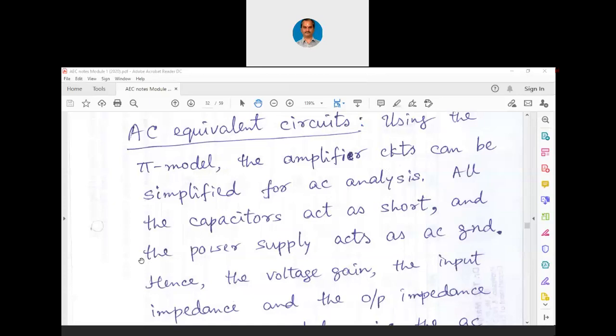In the previous class, we were discussing how to model a transistor in a linear fashion around the Q point. And please recall that we are discussing the small signal operation, where we presume that we are only working around the Q point itself, and there we assume the transistor's behavior to be linear because our operation at the Q point is happening only through an input signal which is of very small amplitude, a few millivolts,